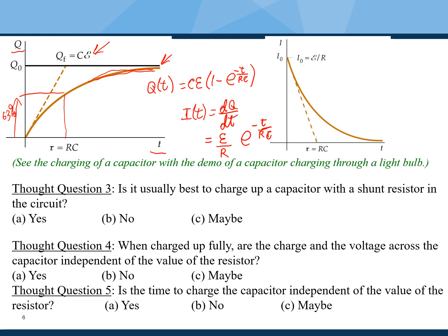And that tells us that the current is initially large and substantial and is given by just the current that we would expect in a resistor which is put into a closed circuit. Eventually, the current decays to 0, and the current decaying to 0 indicates that at a very late time, the RC circuit behaves like an open circuit. In other words, the capacitor behaves like a closed circuit component initially, and at a very late time, it behaves like an open circuit. So this basically reinforces exactly the same things that we have seen before.